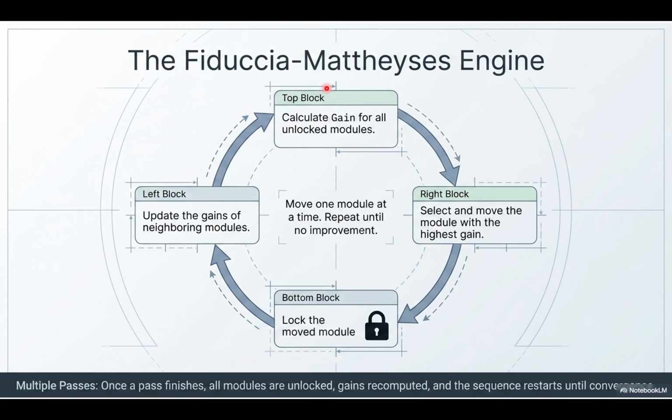or just the FM algorithm. Yeah, FM is foundational. It's an iterative heuristic algorithm, meaning it's not trying to solve the whole universe at once. Right. It doesn't attempt to solve the NP-hard problem globally. It just takes an initial partition, basically a random starting guess, and systematically attempts to improve it by moving one single module at a time. Just one at a time. And the metric driving those moves is called gain, right? Exactly. Gain is the magic number.